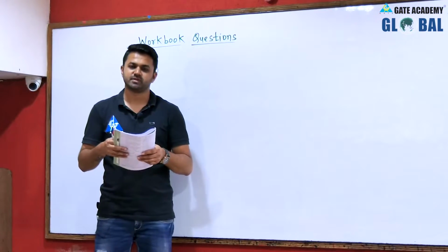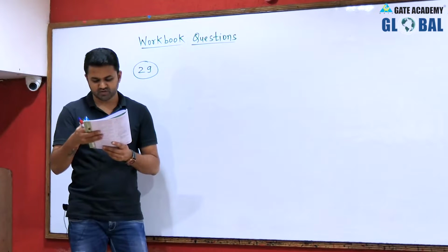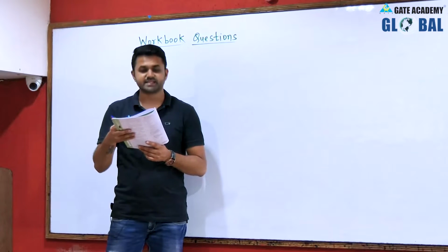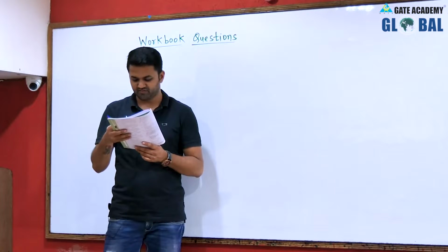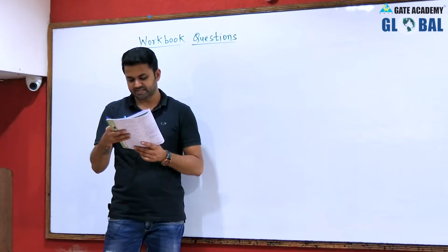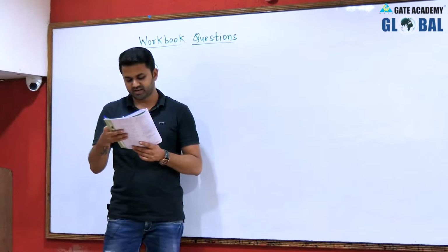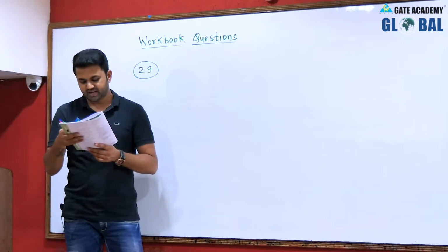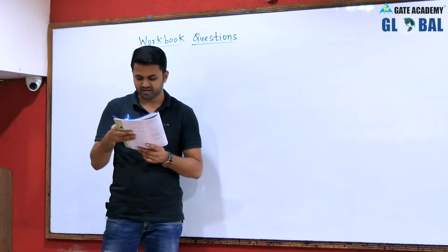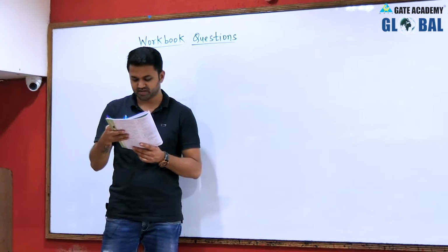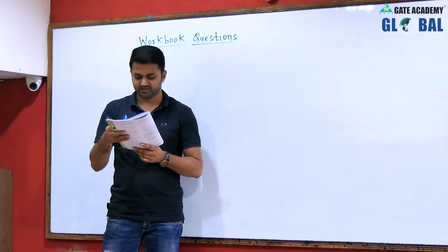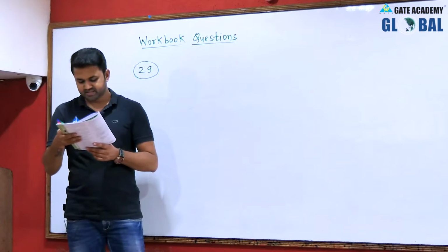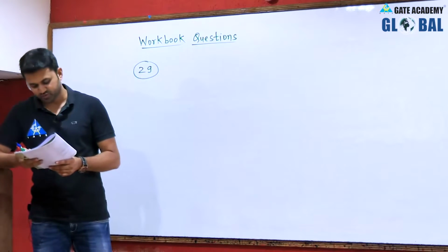So our next question is question number 29. Let c of t equal A_c cos 2 pi f_c t and m of t equal cos 2 pi f_m t. It is given that f_c is very much greater than 5 f_m. The signal c(t) plus m(t) is applied to a nonlinear device whose output v0(t) is related to the input vi(t) as a vi(t) plus b vi squared(t), where a and b are constants. The output of the nonlinear device is passed through an ideal band pass filter with center frequency f_c and bandwidth 3 f_m. To produce an AM signal, it is desired that...